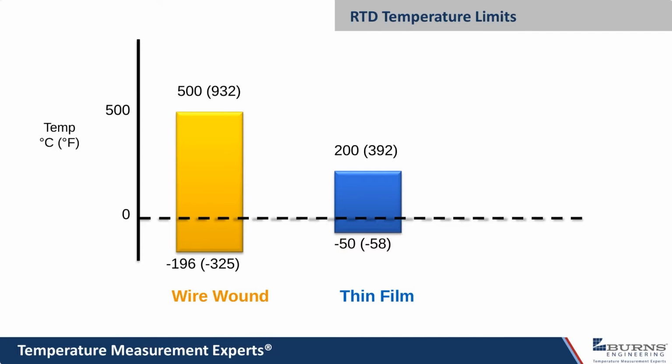The other part of that is a lot of times thin films are made to be more durable, and the materials that you use to do that have the lower temperature limits. Like there might be some silicone rubber or some heat transfer type component, a lot of organic type materials that just have that 200 C or 400 F upper temperature capability.